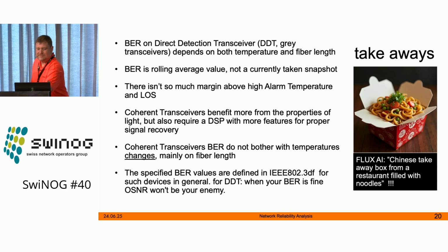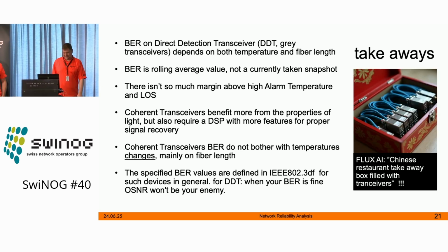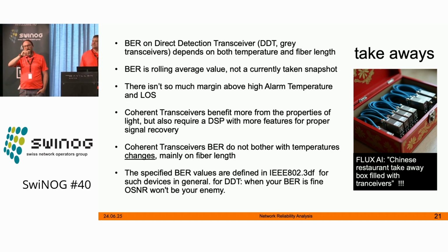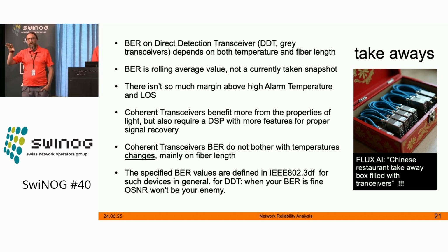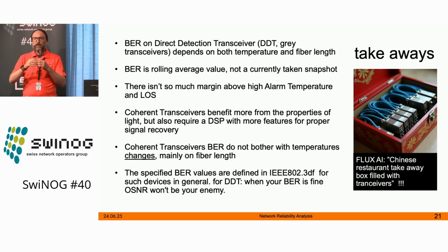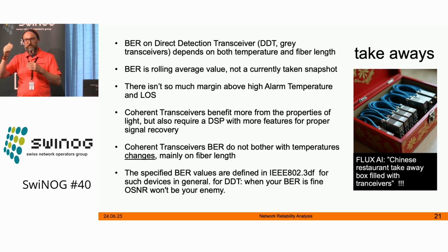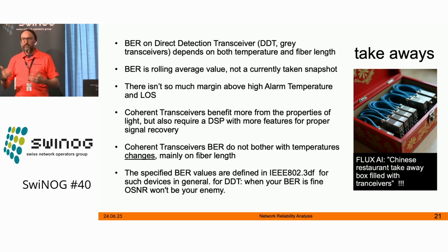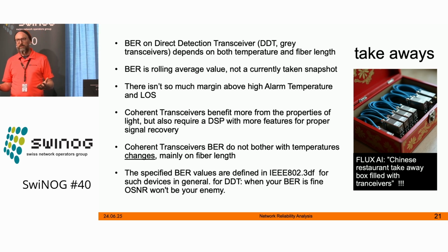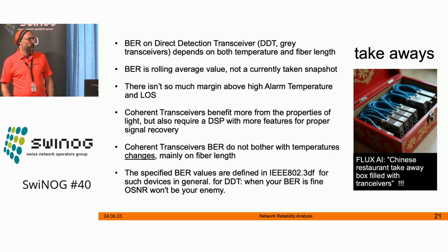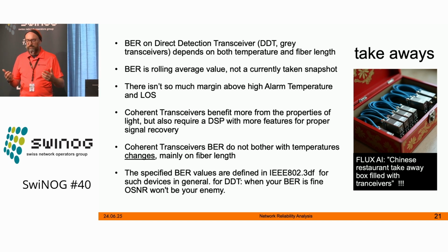Thomas. Okay, and what Gerhard also previously showed when he heated up the transceiver to 120 degrees, you might have seen the 80 degrees where we got the loss event with the transceiver having the DSP inside. So we actually were not able to get to 120 degrees because the DSP has a safety function inside. So when it's getting too hot, it's actually shutting down. And then you get a loss. And that's the point where you're going to look at your gear anyway because the link is gone. So that's more a safety function, which is quite helpful also to protect the DSP.